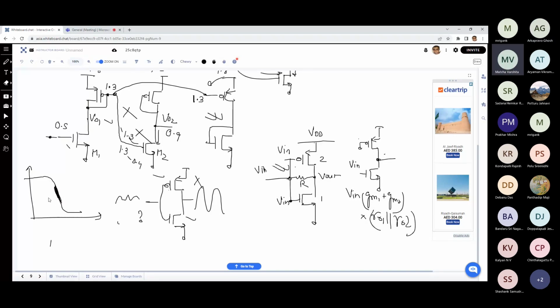In order to get good gains, you need to make sure that the V out equal to V in curve is over here and it is basically cutting this in the center region. I need to bias it, right? Here the output point cannot be biased. I told you the common source amplifier cannot be used with active load directly, single-ended. You can't use it because of bias. Output DC point is not fixed.